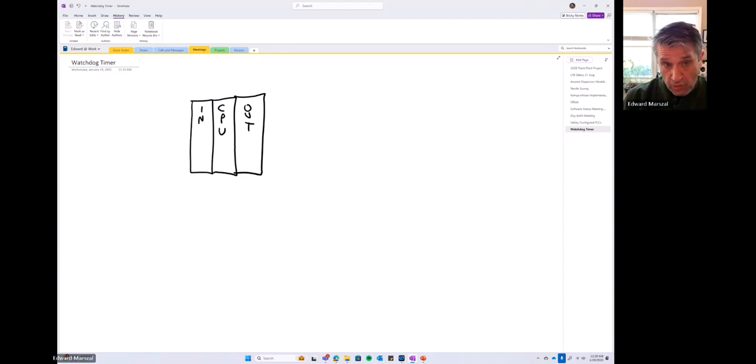So it's going to cycle. And usually we're talking about like 100 milliseconds, maybe 500 milliseconds, depending on what type of PLC you use and how big the program is. That cycle time is going to change. Now, what we're trying to detect is that this CPU is stuck in place. How can I detect that the CPU is stuck in place and not cycling?